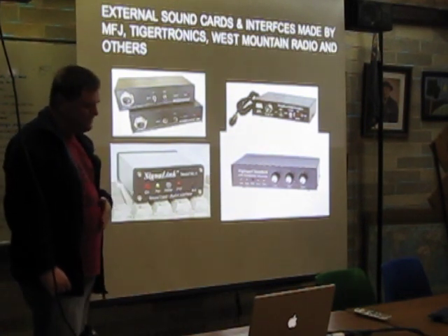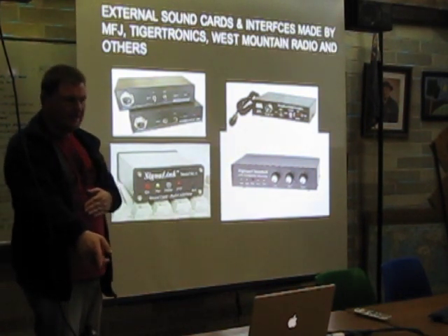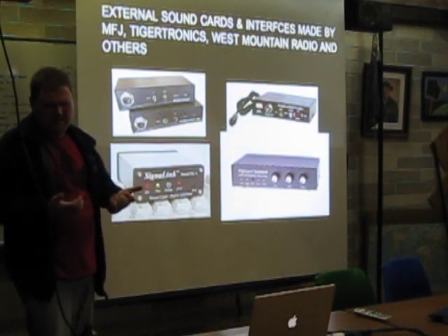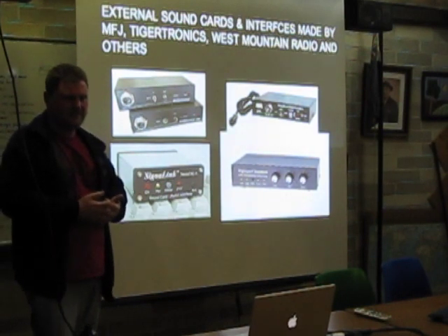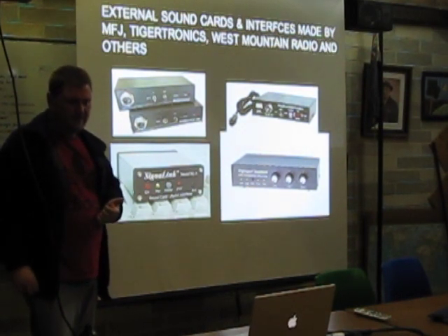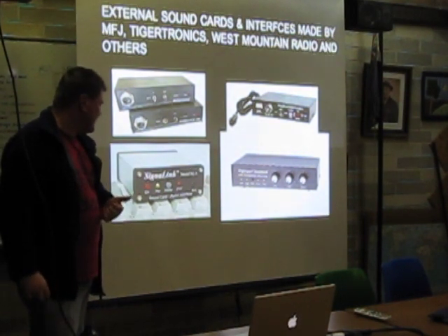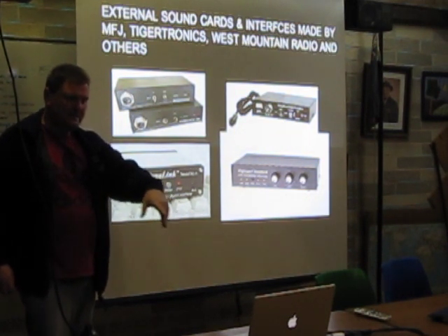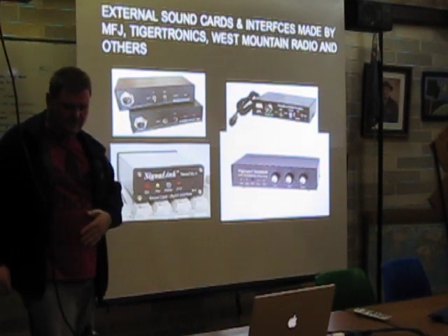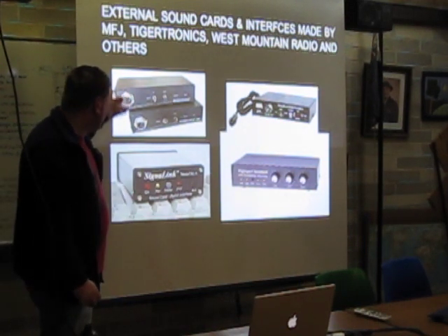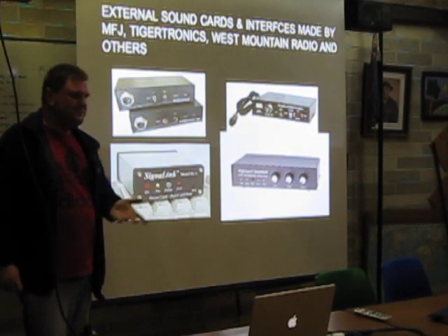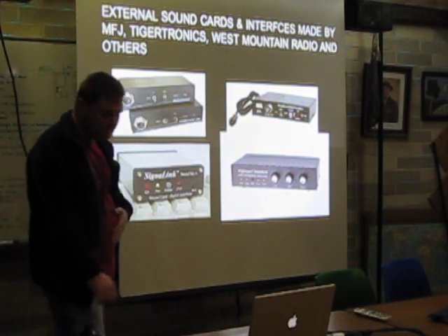You can do that. What I'm doing here on this radio is this radio's got a Vox capability built in. Most modern transceivers do have a Vox circuit in there, so you can use the Vox on your radio as well. Or the other possibility is you have a serial port on your PC and you use the signal from the serial port to trigger the radio. So there are commercial solutions which take care of all this for you, which you can buy in the shop.